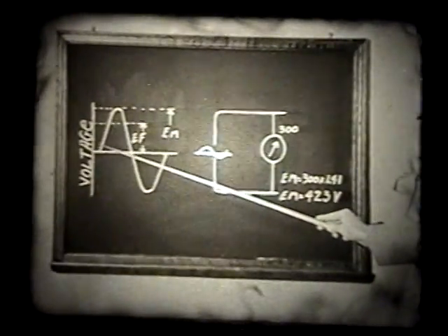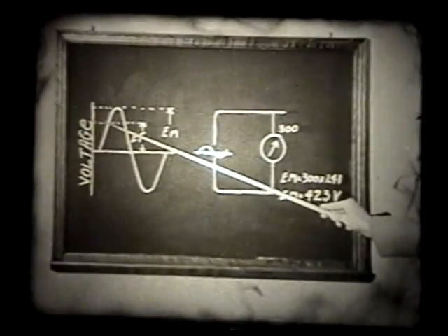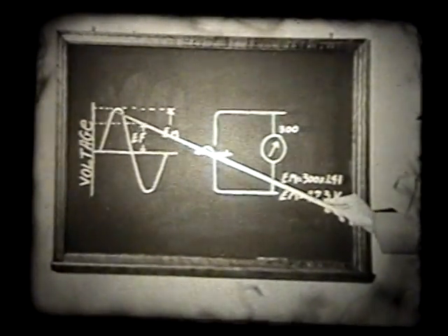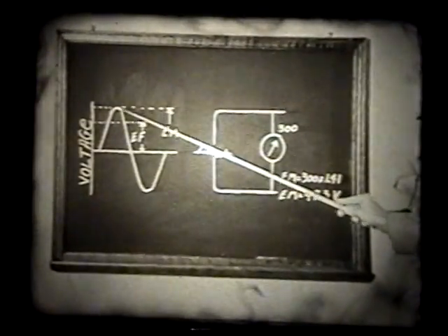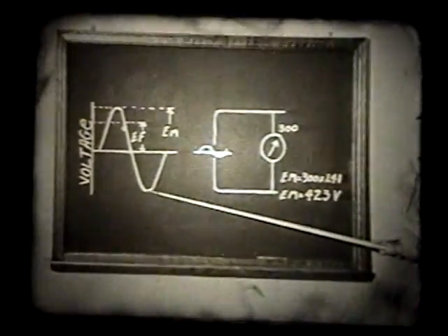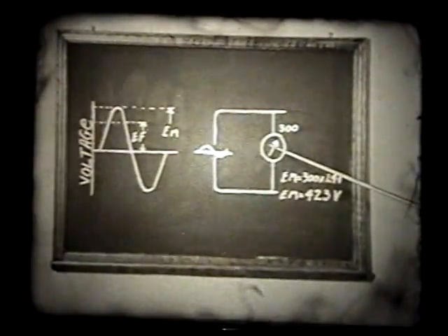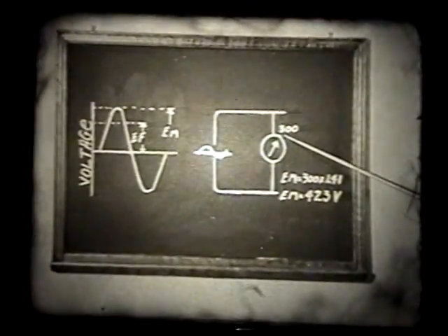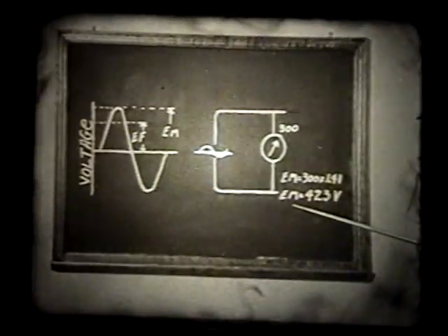Although the meter, at very low frequencies, shows that the voltage varies, it does not leave any residual picture of the changes, nor is it effective at higher frequencies. Even an AC meter, one especially designed to indicate the amount of voltage across an AC circuit, does not give a true indication of the actual voltage changes. Such meters show only the effective voltage value, not the peak voltage.